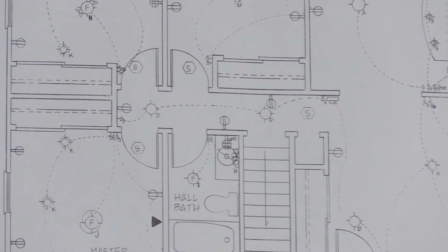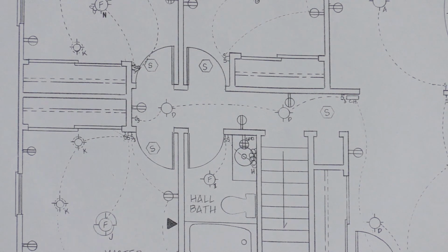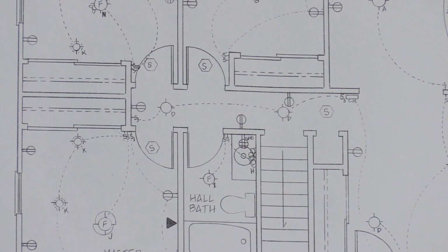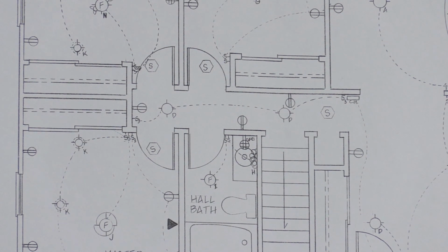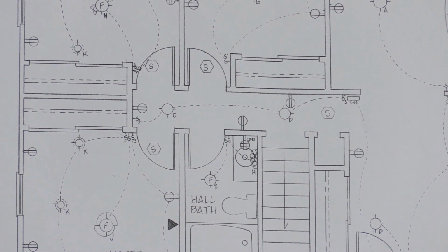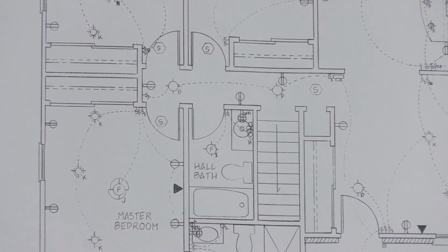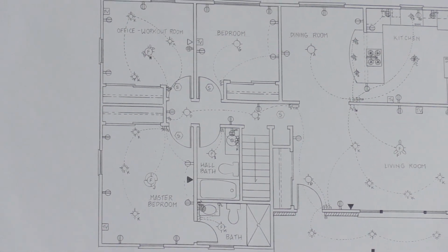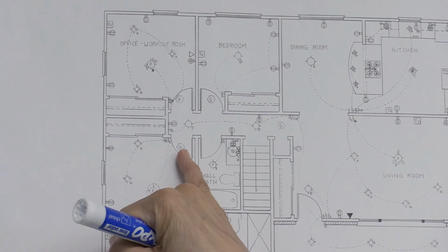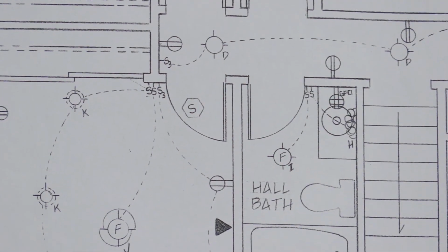The other thing that you have to be careful of, where you locate the smoke detector, is that it has to be more than 4 inches from the wall. You cannot go 4 inches or less near the wall. There's a particular gap in there, because of the way smoke and fire operates, so you want to get that smoke detector more than 4 inches from the wall.